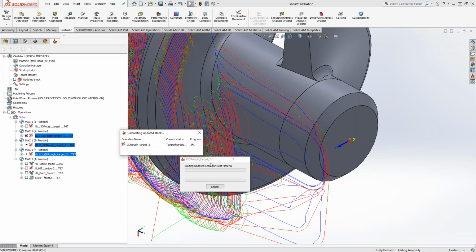Okay, so this is doing one at a time. So there you go. I can't zoom out, but you can kind of see that this one was at the 90-degree area. It's recognizing that some of that stock was already removed from the 0 degrees one, so there's no toolpath over there. It's machining all that. Once this third one is complete, you'll see that it's going to ignore any kind of air over here. And on that fourth one, it should probably look like just a little bit of a straight line. But we can let this calculate.